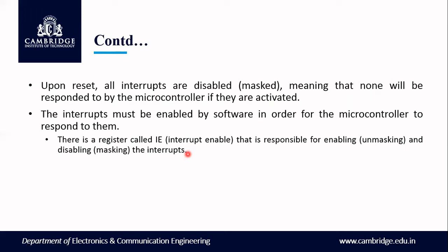So upon reset, all interrupts are disabled. If you are expecting timer interrupts or external interrupts, they will not be accepted by the microcontroller unless you enable the interrupt. This concept is very important. The interrupt must be enabled by software in order for the microcontroller to respond to them. So how do we enable them?